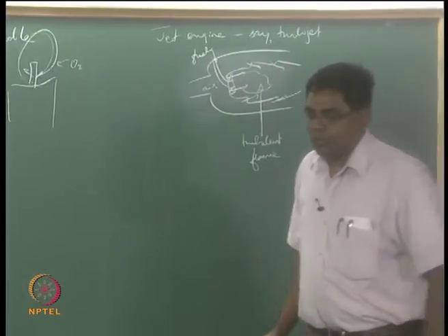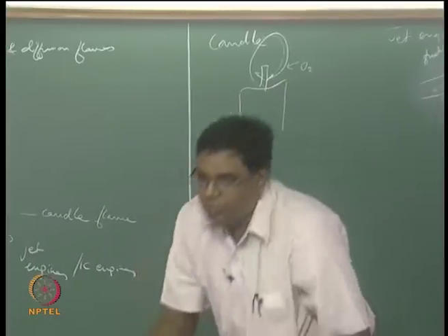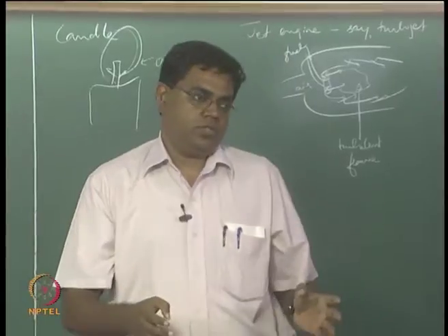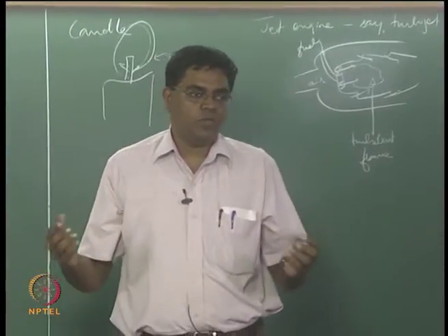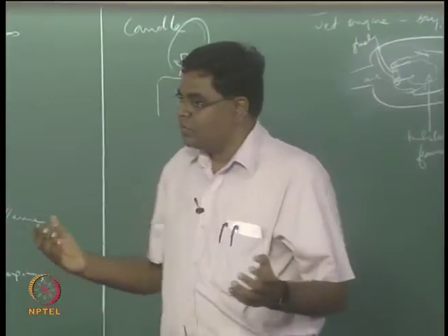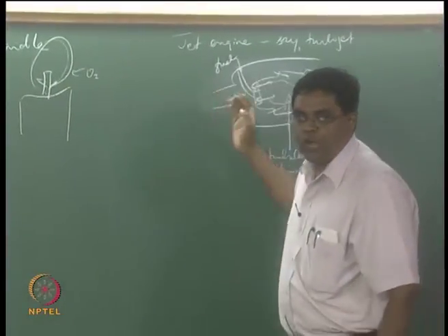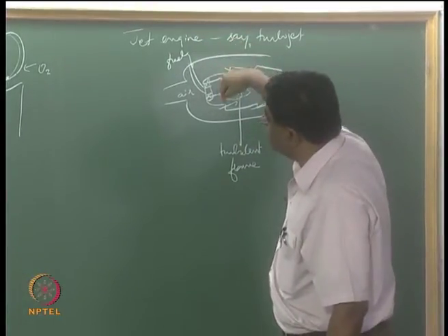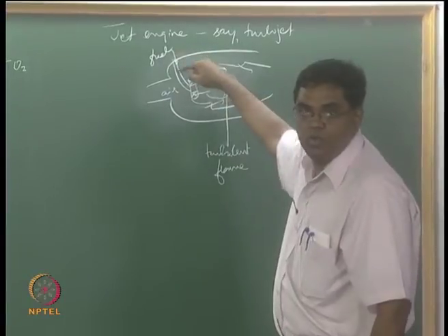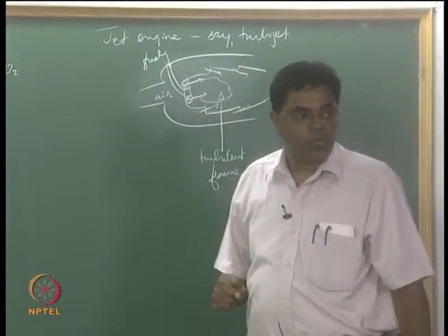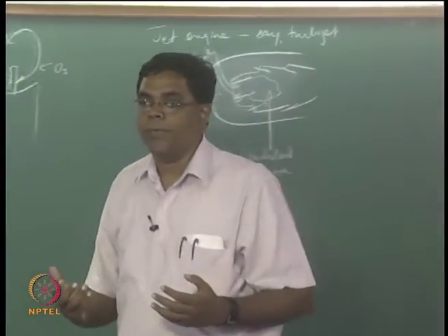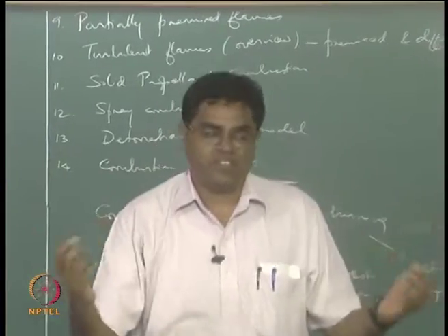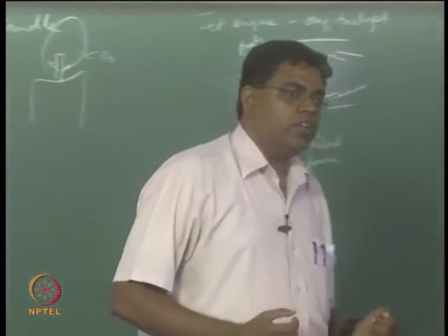So what have we been talking about for the basic elementary processes that constitute combustion? To give you an example of the kind of answer I am looking for, one thing, you have a flow. You have a flow of air through this, and then you have a fuel injection. That means the fuel has to flow through the fuel nozzle and get out there. And then what do the fuel and air do? Not yet. They mix, right?